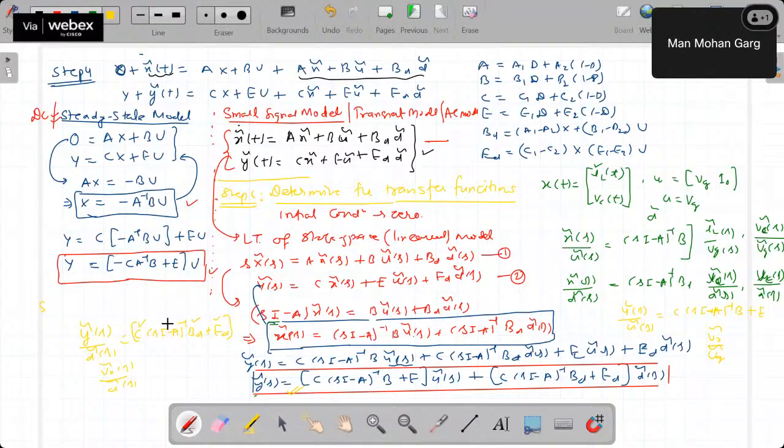Now it's not always necessary that you need to obtain all transfer functions. So what is this transfer function telling? IL of s upon VG of s is telling how the variation in the input voltage, that is disturbance, kind of line disturbance, affects the inductor current. How the disturbance in input voltage affects VC of s, the capacitor voltage. How the disturbance in duty cycle affects this inductor current, affects this voltage. Similarly, how the duty cycle affects the output voltage, and how the changes or variation in input voltage.